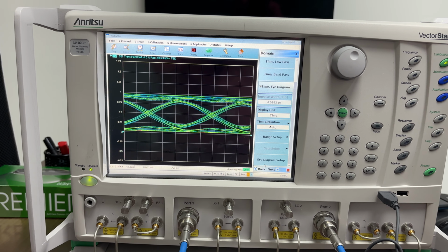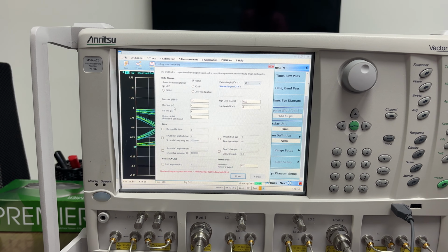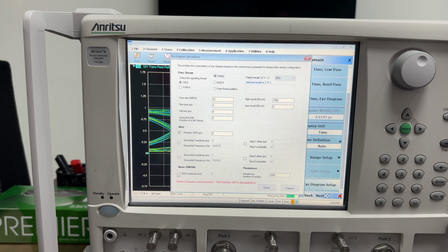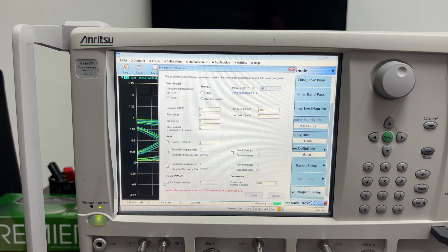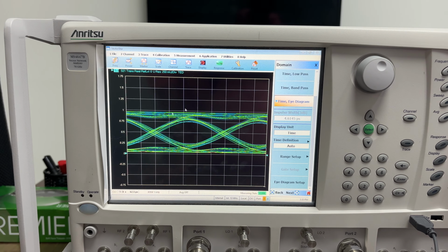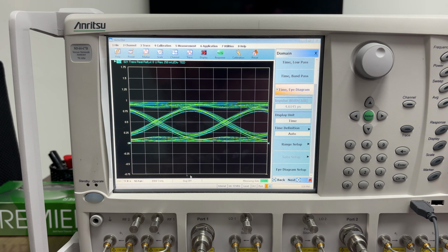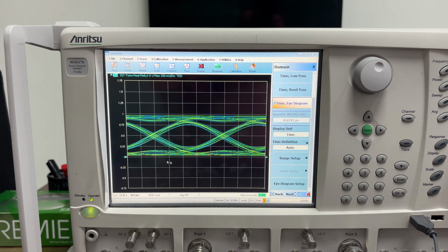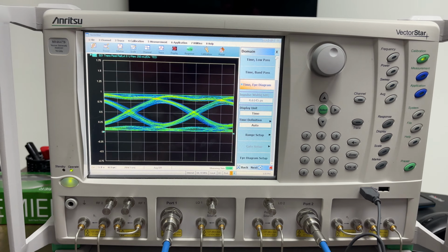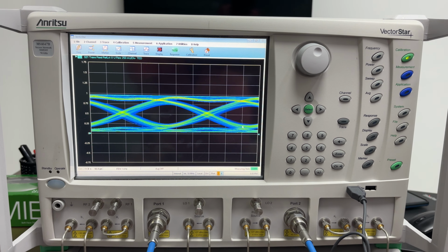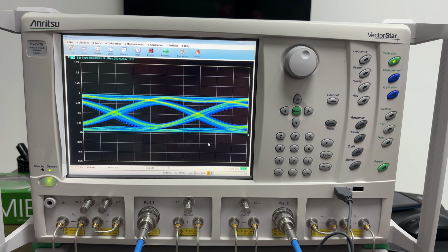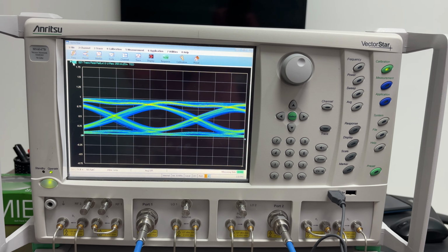In the same way we can see that this transmission line is able to transmit a 32 gigabit signal, but once I add more noise to this signal, you will see that there will be a change, because we are having 25,000 data points. With the 4th or 8th sweep it will change the structure of this measurement. So you can now see, with the addition of this jitter and noise, how the performance is. So this is one of the applications.